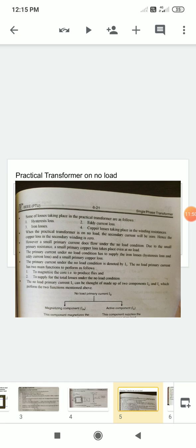Everyone knows whatever supply we are getting from the electricity board, the Punjab State Electricity Board, comes from 66 kV, then there is another substation that may be 11 kV and 33 kV. The 33 kV will be converted into our 240 volt or 400 volt. That is done with the help of a step down transformer that we have already discussed.